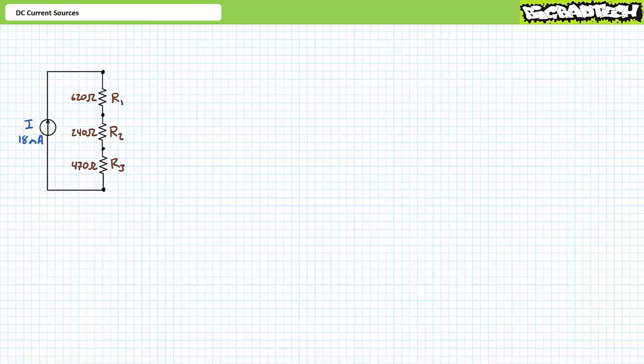This is a totally different circuit than our previous parallel circuits, but well within the reach of those individuals with an understanding of basic series circuit properties and Ohm's law. The most fundamental property of series circuits is that current through elements in series is the same. The current source, being the only active source in our circuit, must therefore induce 18 milliamperes of current through the whole circuit. Source current equals I1, which equals I2, which equals I3, and they all equal 18 milliamperes.